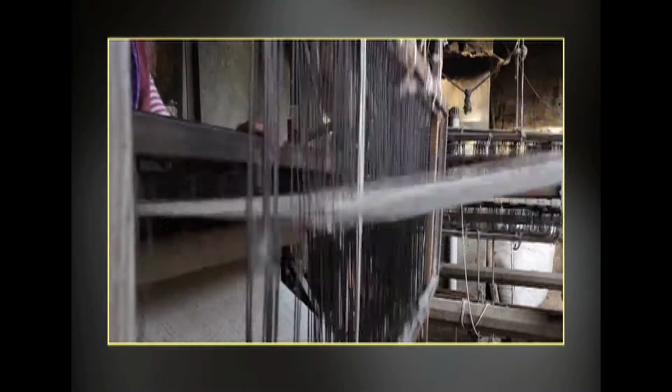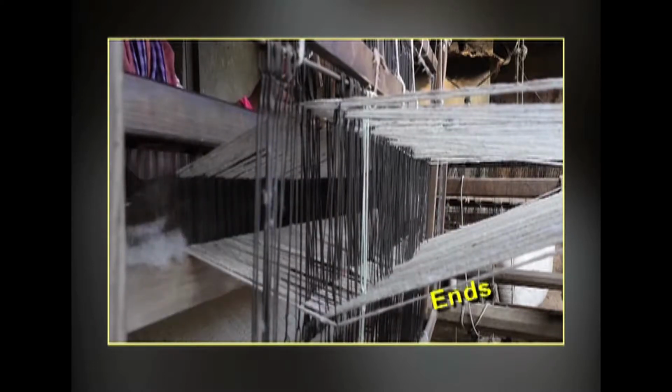And so, usually these warp yarns, which are also called ends, are made a little stronger by using ply yarns. Instead of having one yarn, two yarns are wound together or twisted together to form a yarn which is a little stronger, and it can withstand the strain during the weaving. And then coming to the weft yarn. For example, if the weft yarn is ordinary, then it will usually be a single yarn, unless it is a 2 by 2 and other materials where it is again a ply yarn. Otherwise, in all ordinary fabrics, usually you find it being a single yarn.